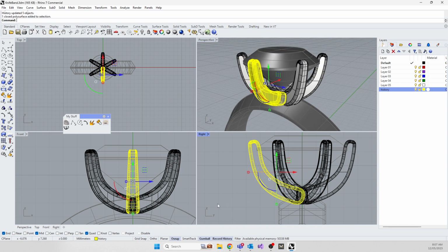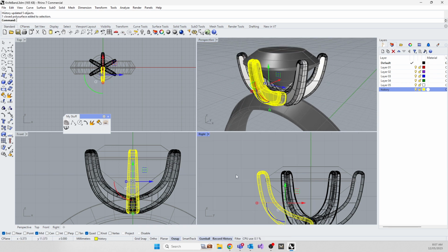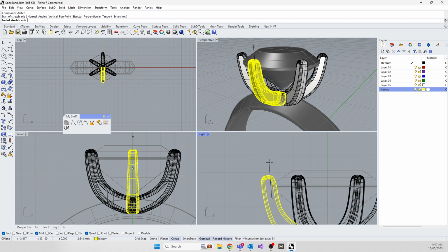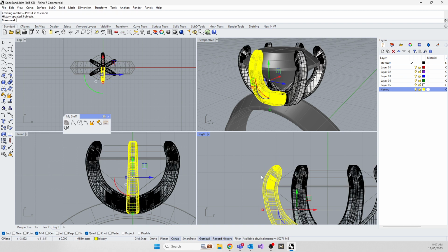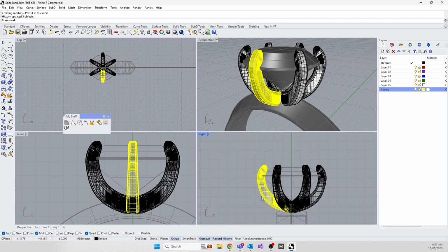All right. So for this guy, if you wanted to, you could use stretch from here to make the prong a little bit taller. You could use bend. Remember the tools we learned yesterday? From here to bend it over the prong a little bit. Many different tools you can use now without breaking the rest of that history. So you use the curve to get you as close as you can in the beginning. And then after that you can play with the rest of Rhino's tools. All right? I stopped that recording for today.